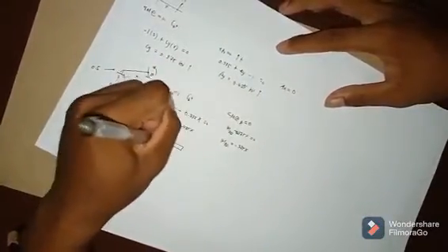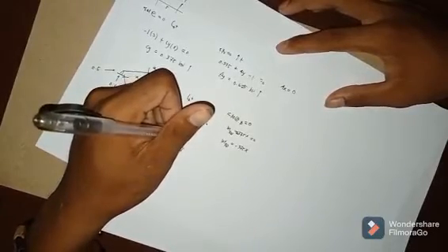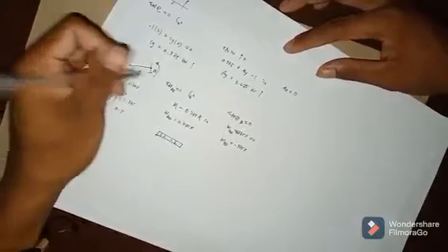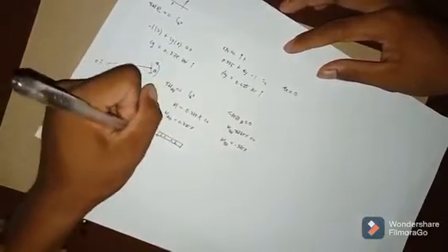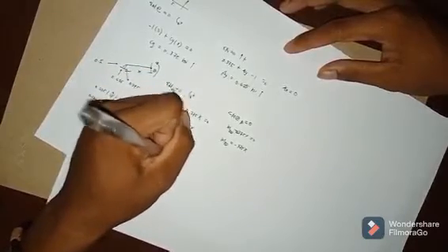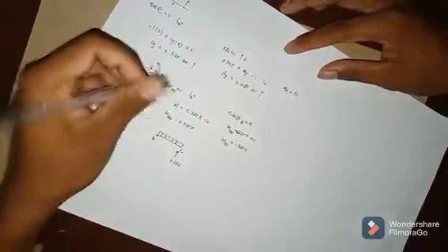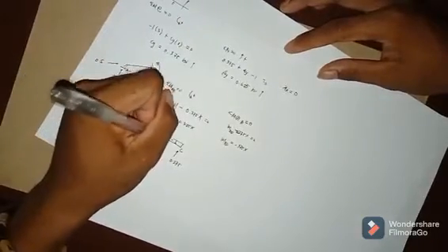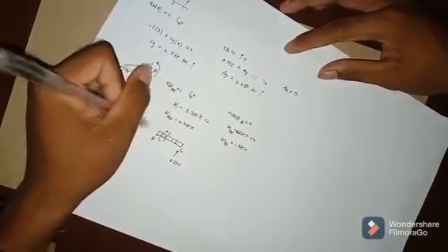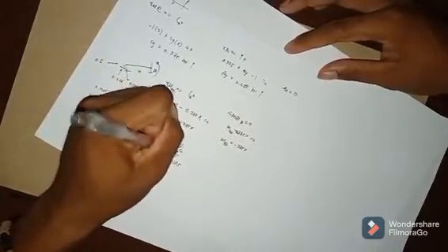So considering this area, it has a concentrated load, and in B and C there's a reaction which is 0.375. If we cut the section here, we can create positive moment which is rotating clockwise, and the length here is considered x.